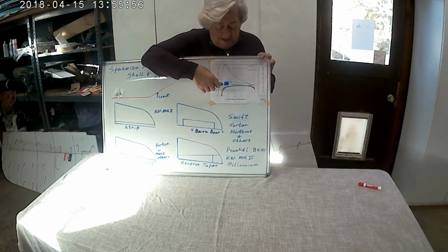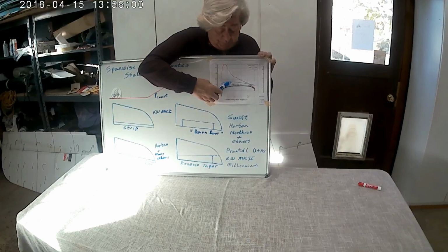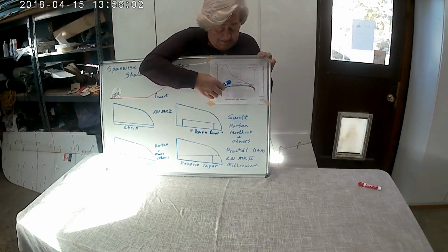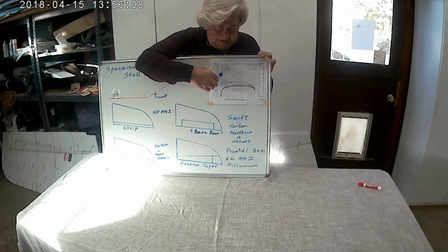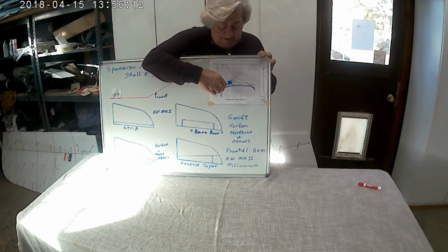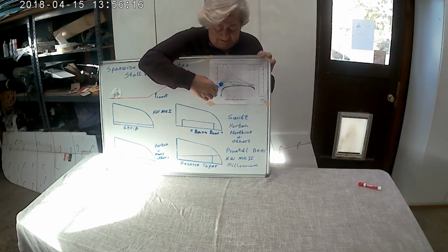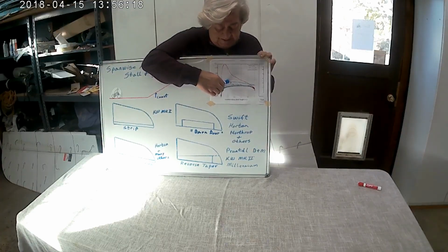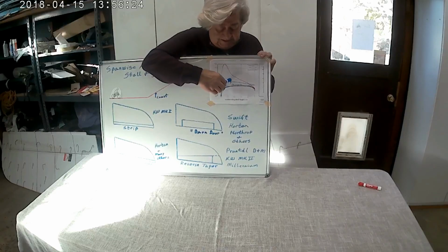In fact, right here at 30% of chord is the maximum thickness point of this airfoil. And that's where the pressure recovery begins. So all of this pressure that was dropped down starting to come back, and then at this point the flow starts slowing up. So accelerating, accelerating, accelerating, no longer accelerating, now decelerating. So this is kind of a coast phase.